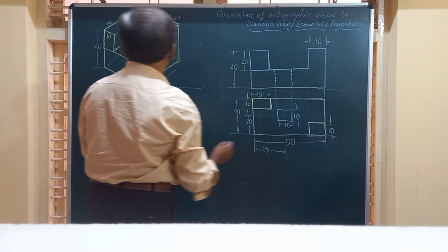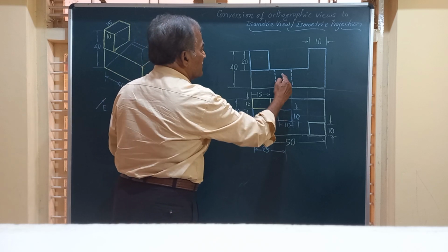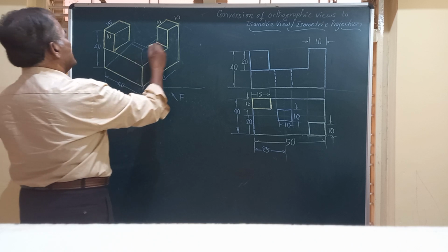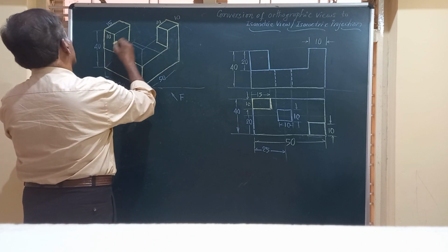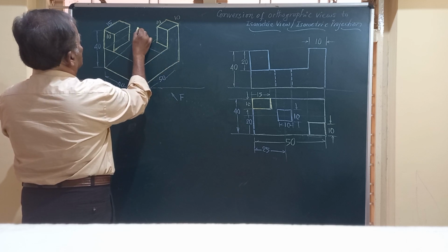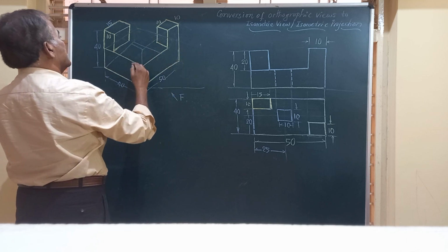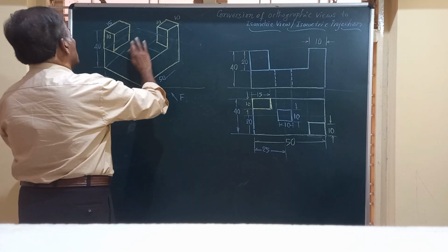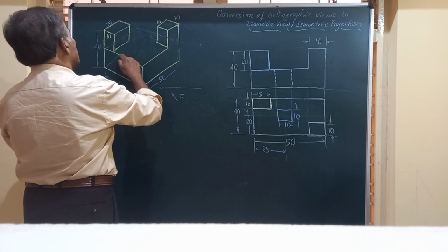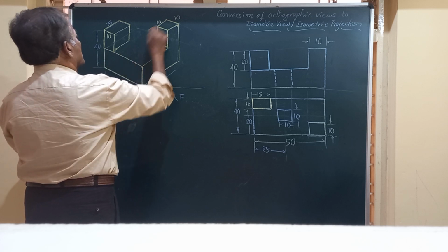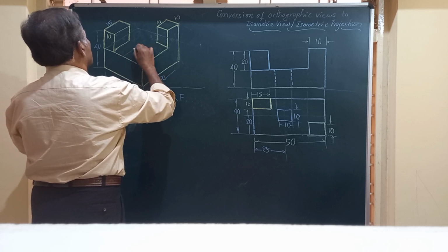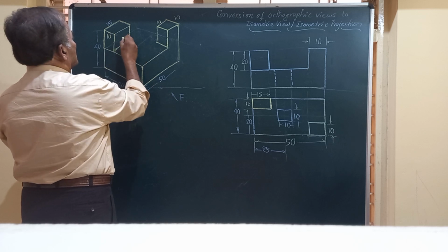That slot is of size 10 by 10, that you can know from here there is a slot. Okay, so we are going to mark exactly in the center of this. Say if we extend this line by thin line, we had a line like that, friends, exactly in the center of this block, which can be marked by joining the center of this line to the center of this. You are going to have the block divided into two equal parts.